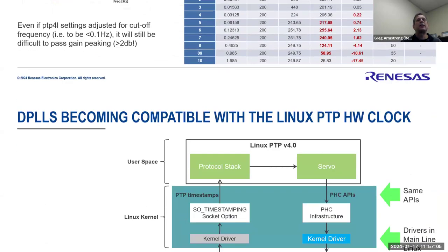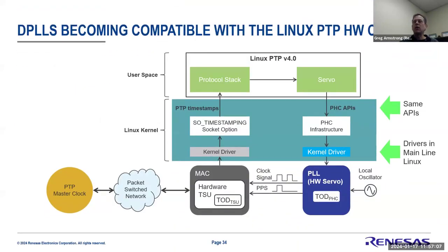So that's why you're starting to see the introduction of hardware-based PLLs for use in 1588 applications. So very common in telecom, but you're even starting to see it introduced even into the data centers, right? You're seeing PLLs being put down onto NIC cards in order to do some of the filtering. Some of it might be for physical layer clocking, but it actually could be used for packet-based clocking and filtering as well. And so that's kind of some of the things that you can start getting.